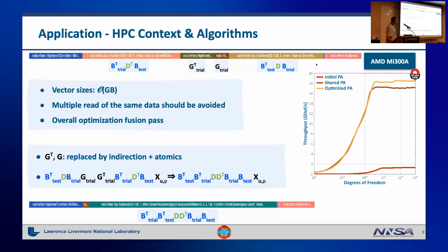One big constraint at this level is the size of each vector. When you're at the million degrees of freedom level, you don't really care about the size of the vectors, or the size of the geometric factors that lie under the hood in MFEM, in some of the caches. Here, you cannot just leave it like this.